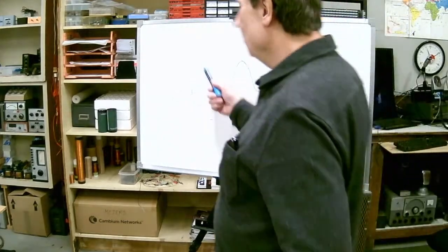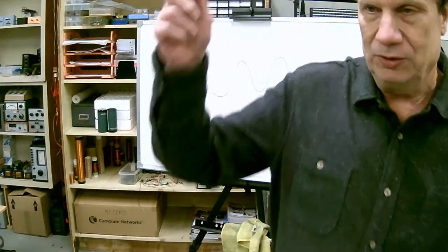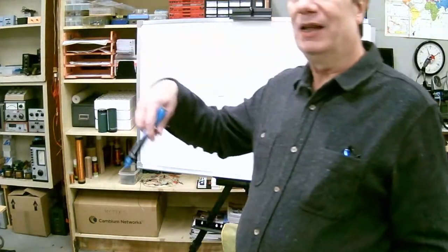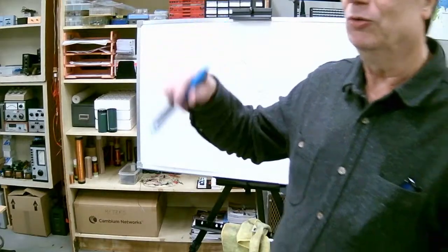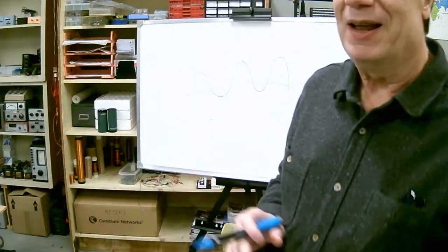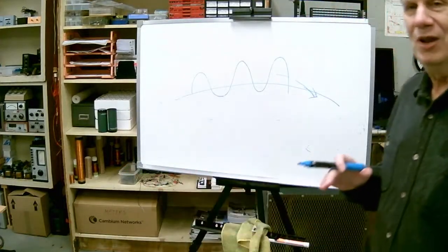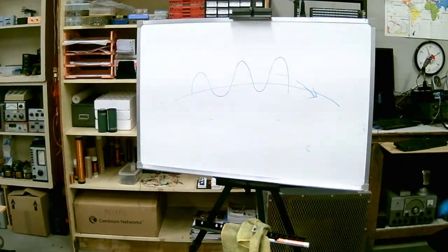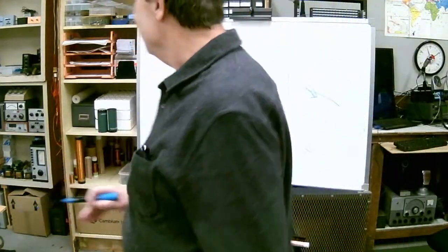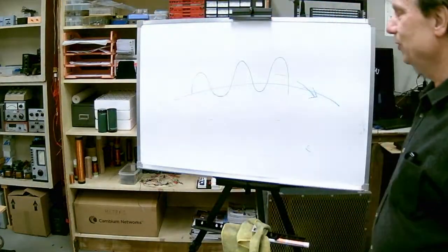And so it's vertically polarized, which means the electric field is going to be vertical. Or if you're radiating from an AM antenna, it's going to be the same. The polarization is always going to be the same direction as the wire you have. Now, there are pure magnetic antennas where the polarization is not defined by the physical orientation of the wire, but for almost anything we're going to be working with, if the wire is vertical, the polarization is vertical. So that's going to be the electric field here.